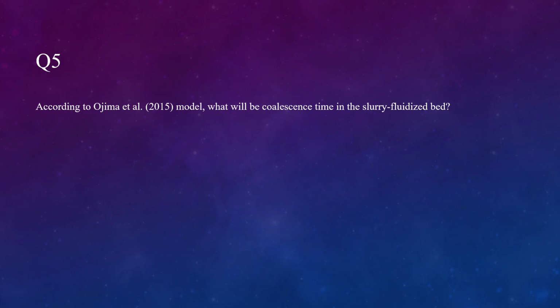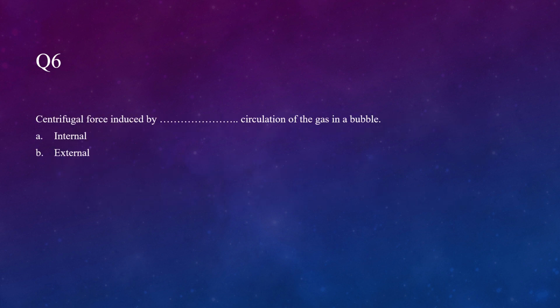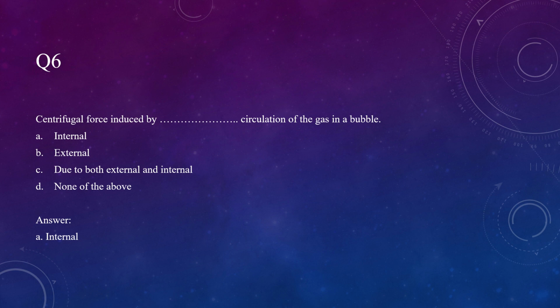Ojima et al. model: coalescence time is dependent on slurry concentration, as coalescence time decreases as slurry concentration increases. So the explanation is given over here. Centrifugal force is induced because of the internal circulation of the gas inside the bubble, sorry, not inside the bed, inside the bubble.